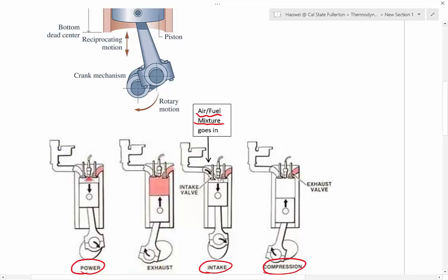So that's why usually for a gas engine, combustion happens at constant volume, because it is so quick. It doesn't give time for the piston to move yet. And then after the combustion is completed, the gas will expand. So that is the second step within the power stroke. That is an expansion process, pushing down the piston. So that is the power stroke.